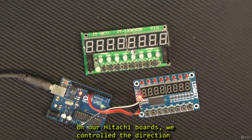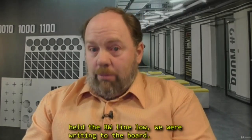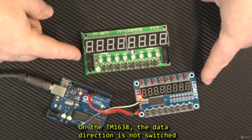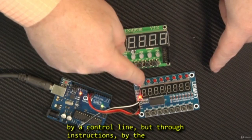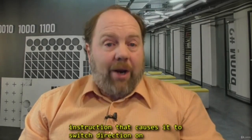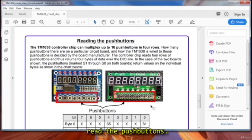Now on our Hitachi boards, we controlled the direction of the data lines using the read-write line. If we held the RW line low, we were writing to the board. If we held the RW line high, we were reading the board. On the TM1638, the data direction is not switched by a control line, but through instructions by the controller itself. There is only one instruction that causes it to switch direction on the digital input-output line, and that's hex 42, the instruction to read the push buttons.